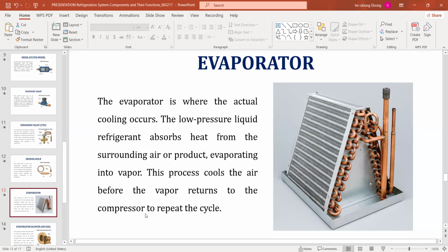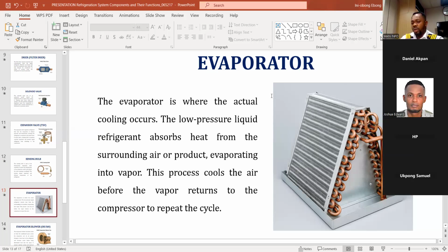Somebody asked a question yesterday which we did not answer. It was about this icing up. What really happens is that when people notice ice on the pipe, they just assume it's refrigerant and you need to top up. But that's not true. You should be able to identify the high side and the low side pipe, and understand the system, so that even without using your manifold gauge, you can tell when you need to top up refrigerant or check for leaks.